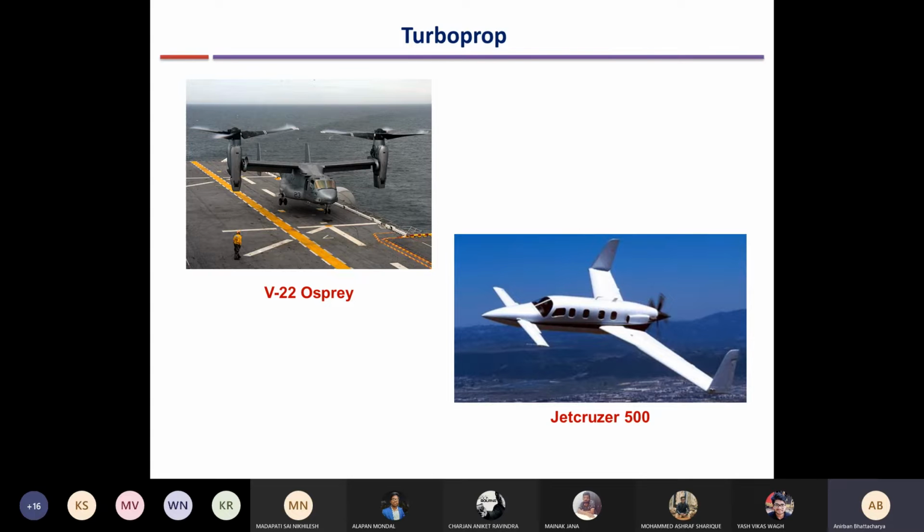And on distances, theoretically it is possible to use supersonic aircraft for large distances, but turbofans have even larger efficiency, and they operate at their best when it is just subsonic. So that's why supersonic passenger aircraft are not used. But for military purposes, you need very high speed during certain maneuvers, like when you are engaging another aircraft or want to evade a missile. You need a very large amount of speed, and at that time, turbojet engines make more sense.